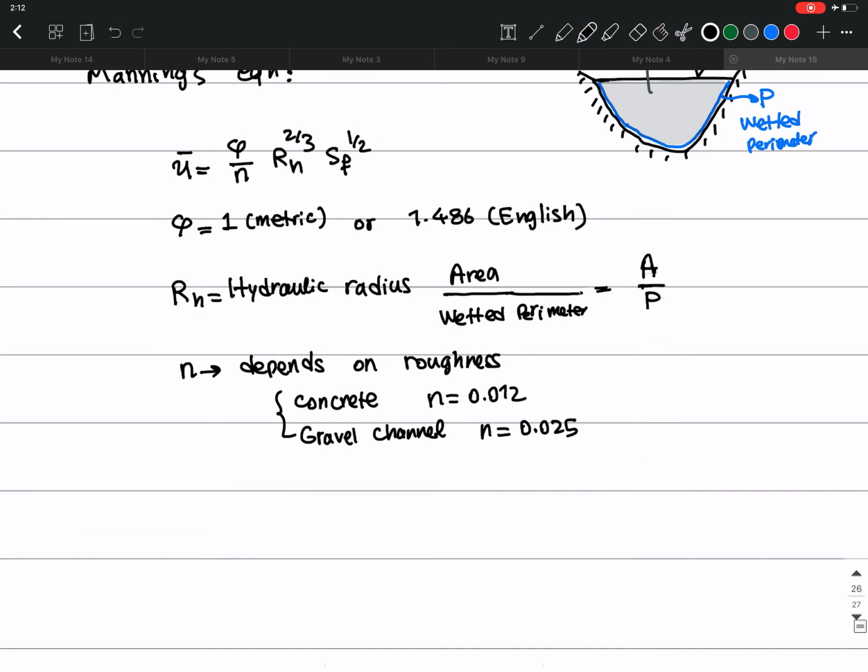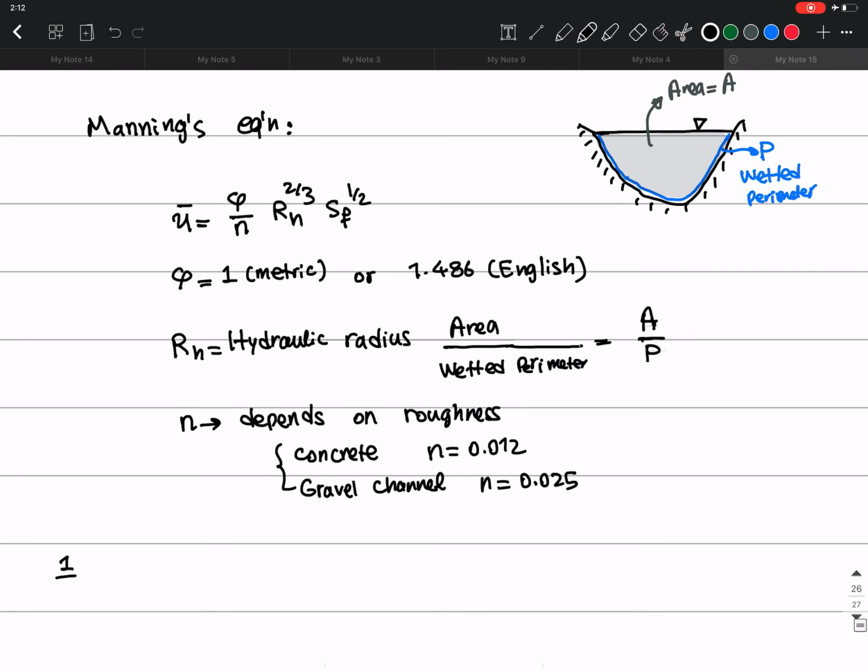So now we have this force, this 1 over rho of F viscous. We can write this in terms of the wall shear stress, okay? And then use the surface friction from Manning's equation to get it. So this is what we typically do.